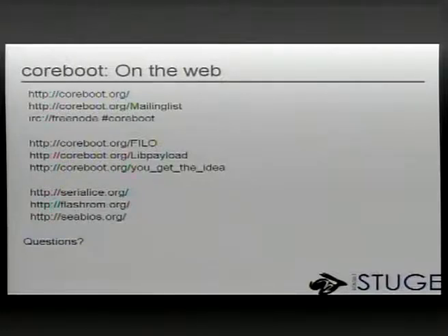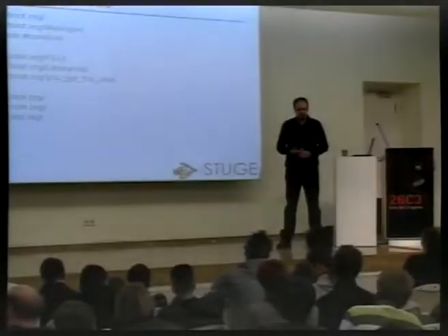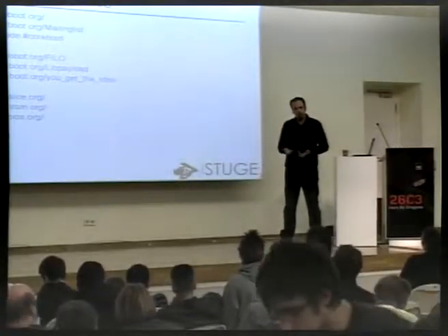Okay, one question is: is coreboot FS writable? So the normal way you use coreboot FS is this CBFS tool utility, which you use to put files into a coreboot FS image, and then you flash that image to a flash chip. I see in the future that CBFS tool and FlashROM will merge somehow, so that you can do the same operation, but that you can do it directly on a flash chip. In theory, it's writable in flash. Yeah, sure. So does that answer your question?